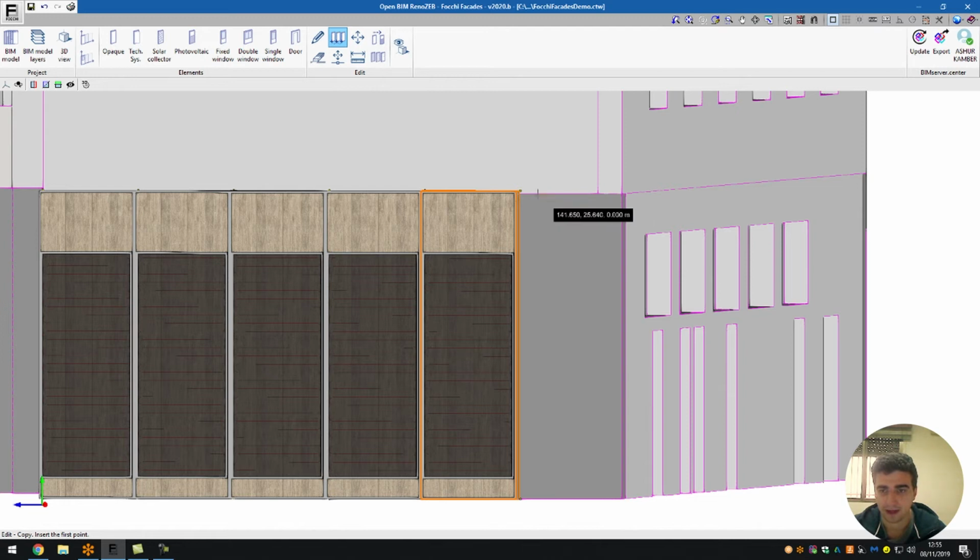So once I've done that, let me left click, and now I'm able to move it. Now I'm able to move and specify the final destination of where I want it to be. What might happen is that you might not be able to place it correctly straight. A little shortcut for that is holding down the shift key. By holding down the shift key, I'm specifying that my wall will exist at right angles.